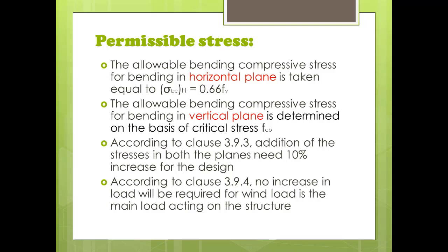And the last one, it is said that according to clause 3.9.4, where the wind load is the main load acting on the structure, no increase in the permissible stresses will be allowed.